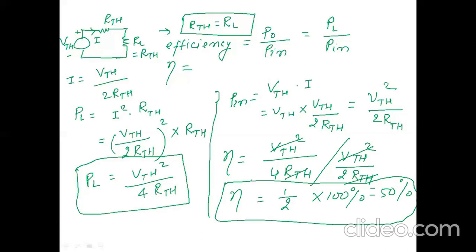However, in electronic devices, the objective is to obtain maximum power output irrespective of device efficiency, and hence this condition is always used at the power stage of an electronic system. Of course, the 50% power lost in the system, device and component must be suitably dissipated to limit the temperature rise. So this type of efficiency we are using only for electronic circuits, because efficiency is too low.